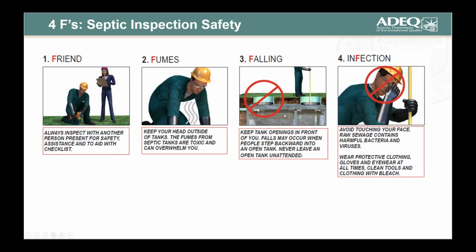Okay, let's consider the safety issue of falling. You don't want to fall inside an opening, so you want to keep septic tank openings in front of you. Falls may occur when people step backward into an open tank. Therefore, never leave an open tank unattended, and preferably put a lid over the one that you're not using, and only have one of the access openings open at a time.